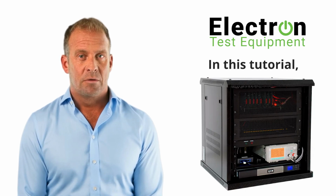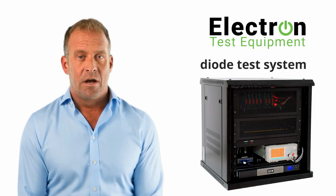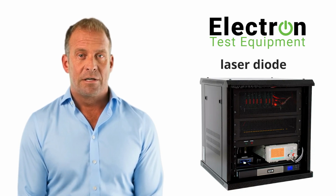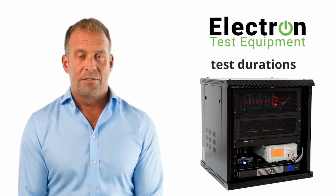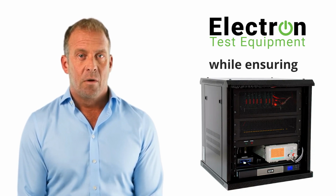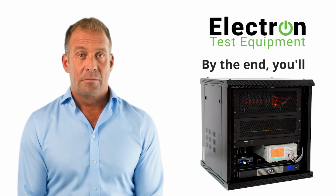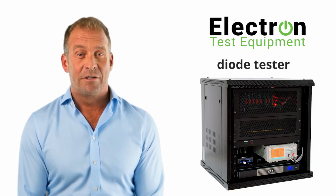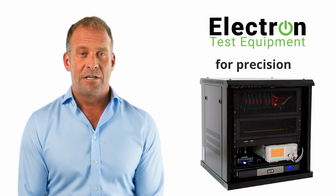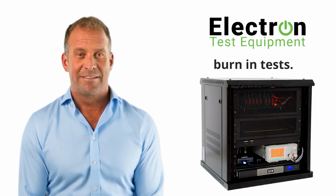In this tutorial, we'll show you how to configure the testing parameters of the ATE laser diode test system for batch laser diode testing and laser diode reliability. You'll learn how to set up sample selection, read intervals, test durations, and laser diode currents while ensuring safety limits and ACC mode are correctly configured. By the end, you'll confidently perform and monitor reliability tests with our laser diode tester, designed for precision in laser diode performance analysis and laser diode burn-in tests.